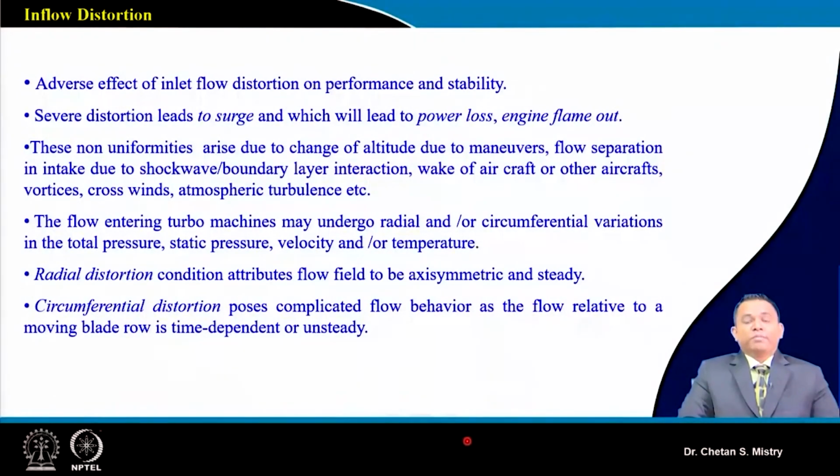Now this is happening mainly for engines because of radial or circumferential variation of total pressure, static pressure, maybe velocity or temperature. So change of any of these properties is what will bring inflow distortion.